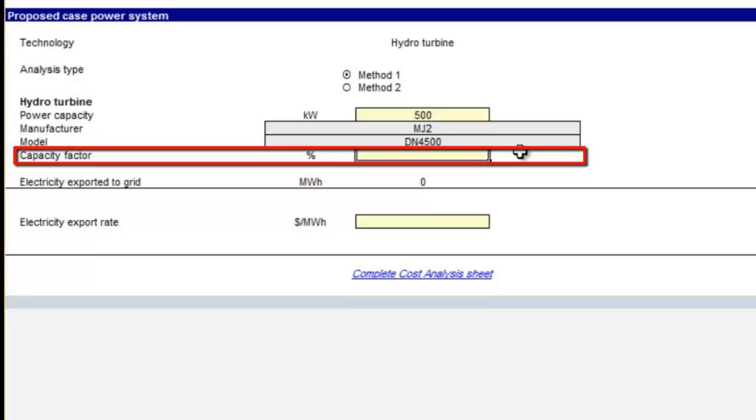Provided that there are no restrictions on the maximum output of a hydro plant, the optimum size of the plant will depend primarily on the availability of water. At some point, the cost of building a larger plant cannot be justified by the resulting increase in energy production. Typically, for a run-of-river hydro plant, this point is usually close to the mean flow at the site.